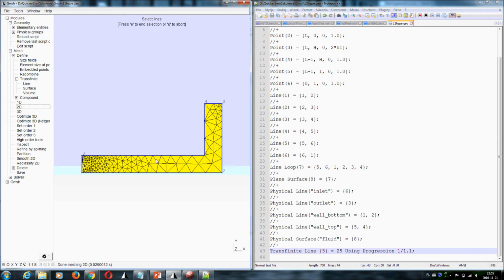So we would like to have really small elements here, so we would like to have big mesh resolution, but this is where you can't choose the size of the elements at the point or the number of subdivisions on the line, because you want to refine your mesh somewhere inside of the domain. So size fields is the thing that you need.